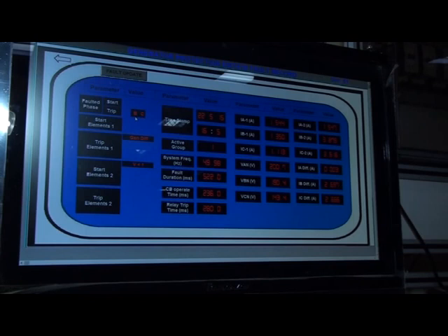Fault date, time, fault duration and relay trip time information can be observed on the SCADA screen. Here we performed an experiment showing how differential current becomes abnormal, like 2.3 ampere, 2.9 ampere, and then the relay immediately protects the generator. Normally it should be like IA differential current 0.003.